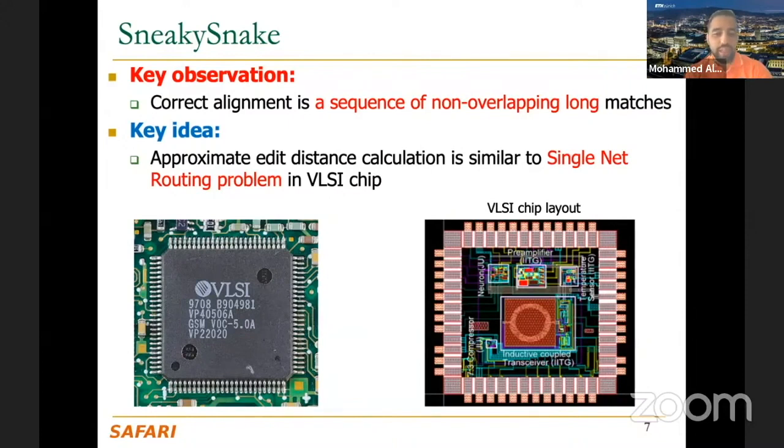It could be the lowest latency, the minimum energy consumption, or the least routing cost, for example, because for these routing paths you pay a cost, right? And you don't want to increase their number because they will increase the energy or take space because they will collide with those modules. So your goal is to find the shortest path from one point to another point while connecting some of these components or avoiding these components. It depends on your design schema. So that is the single net routing problem.